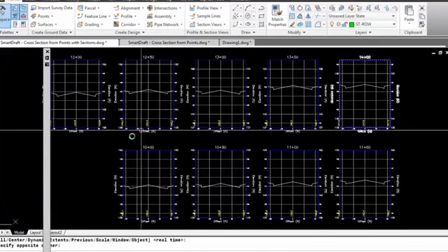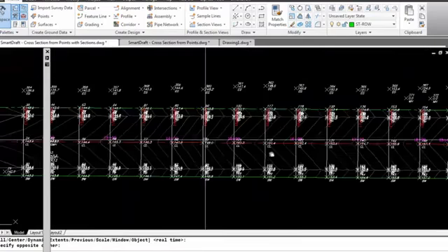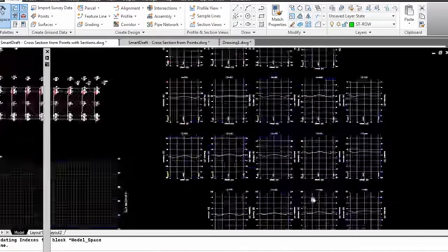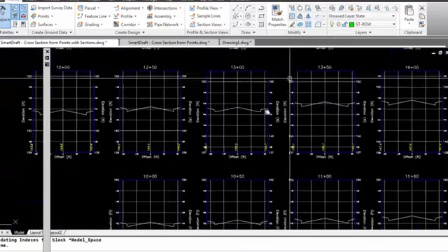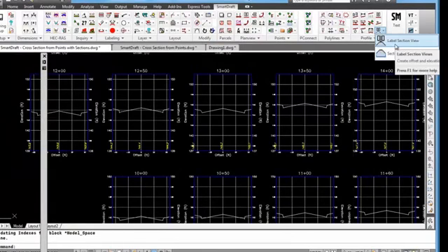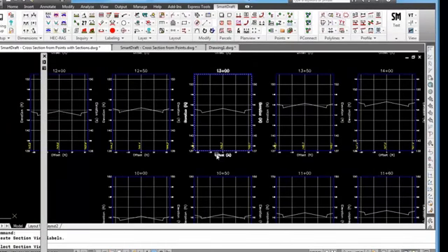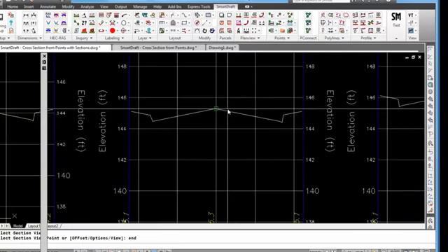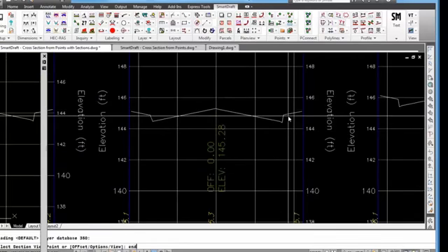Sections from the section views. You see it's the same surface here that we have from the other file, but here I've already output my section views that were created. SmartDraft did add in the profile tools a section view label tool so that you can specify the section view and pick points, label more on this type of setup if you want to.